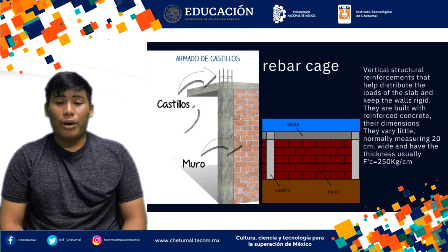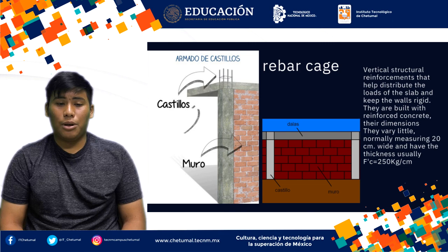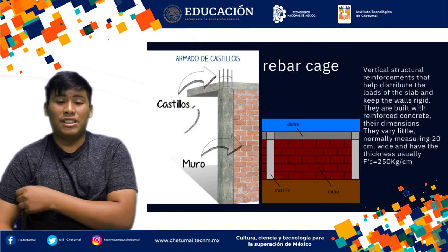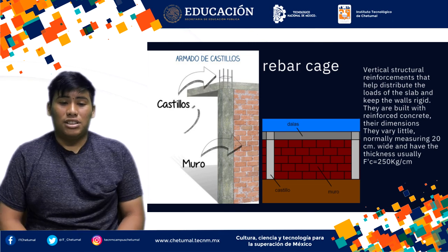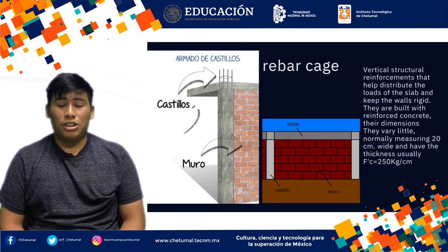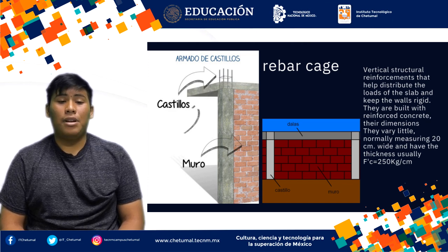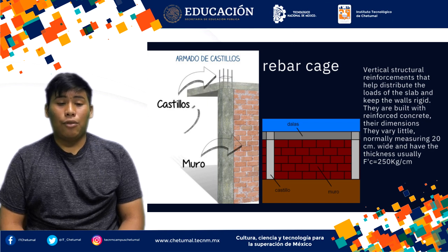Visual: workers preparing and pouring the concrete floor slab on a construction site, showing the compaction and leveling process. The concrete floor slab is a layer of concrete placed directly on the compacted soil before laying the final floor. Its purpose is to provide a stable and resistant base. The construction process: first, the ground is compacted to prevent future settlements. Then a concrete layer 10 to 15 centimeters thick is placed. In some cases, reinforcement mesh is used to give it greater strength. Importance of the concrete slab: in addition to providing a level surface for floor construction, the concrete slab acts as a moisture barrier and helps